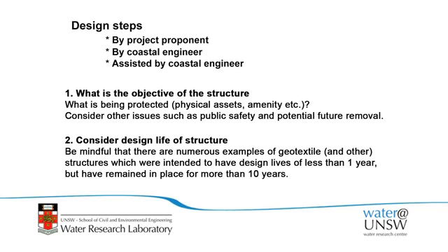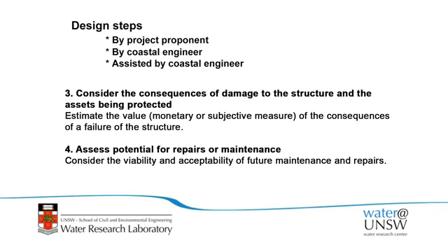down the track. Second step is to consider the design life of the structure, being very wary of the example I showed of Stockton, where often that's far exceeded, but nevertheless, at least consider what the design life you intend to have for the structure is, and realise that may well be extended far beyond what you originally intended. Also consider or document the consequences of damage to the structure or the assets that are being protected. So again, you need to at least justify in some sense, whether monetary or through a subjective measure, what it is you're trying to protect.